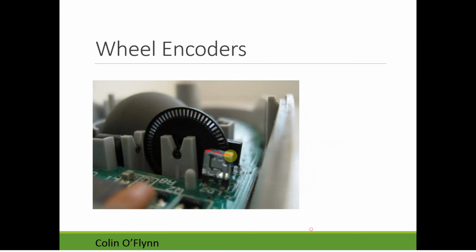and there's an infrared transmitter and receiver. I don't know which is which. This one's probably the receiver because it's black, so it's shielding from everything but IR light. All it's doing is looking for a big pulse, then nothing, big pulse, then nothing, and I know that this wheel has moved past a certain number of times. So all it's doing is counting the ticks in that wheel.